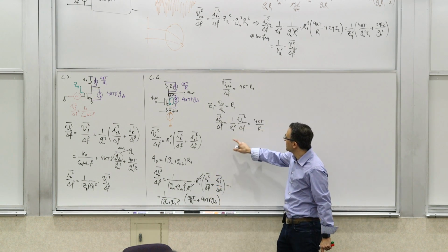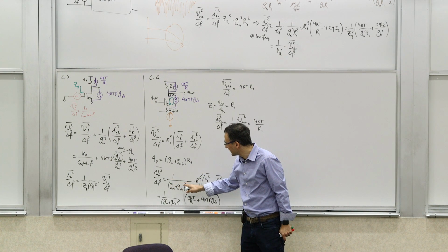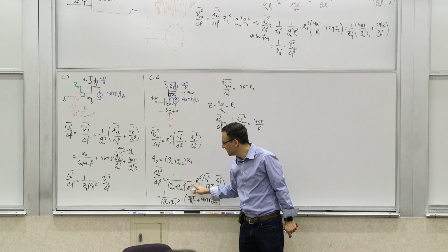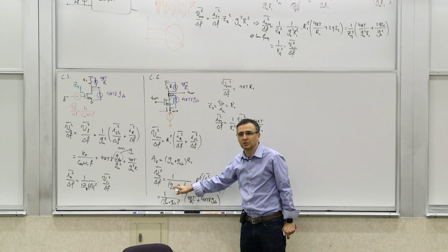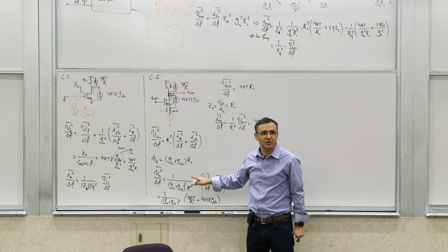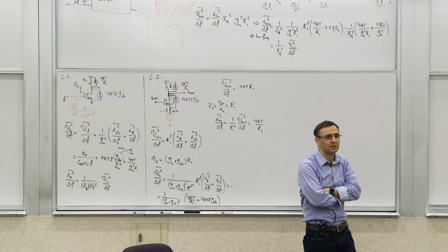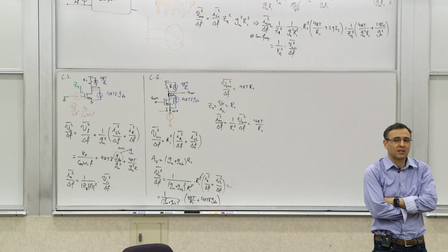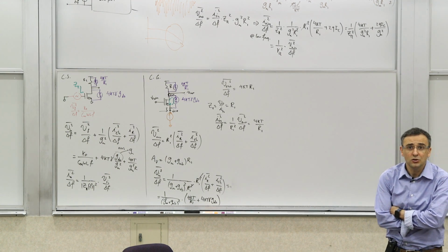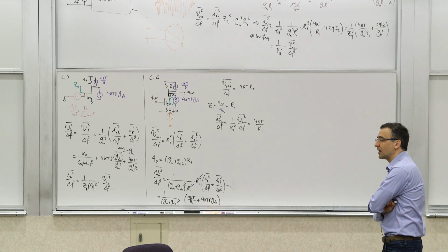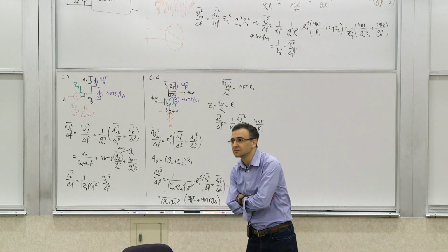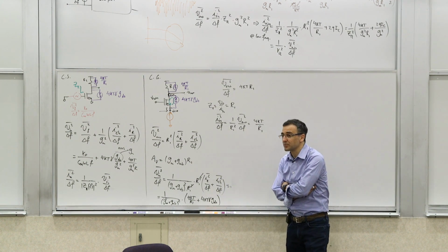You see, here there's an attenuation of the voltage by the gain, by this quantity, right? When it's referred to the input. There is no such attenuation for the current. And that's one of the weaknesses of the common gate amplifier stage. And it's still used. It can be used even in low noise amplifier design, but you need to be aware of that. Right? So that's one observation.